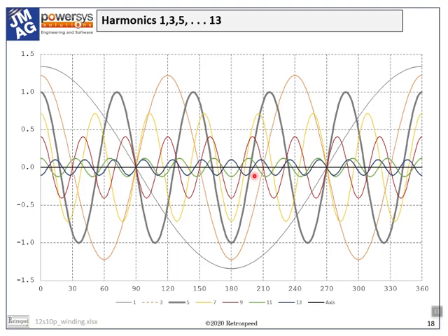Also, it's important to note that this analysis is for one pair of coils in one phase, really just the first row of connections in the earlier slide, giving us a 6-coil winding with one coil side per slot. When we add the second row of connections, we will find that the fifth harmonic is reinforced while many of the others are attenuated.